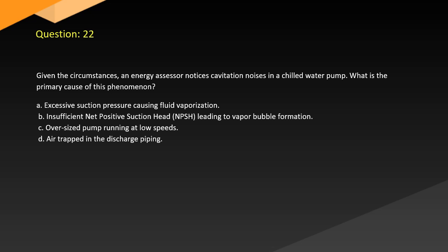Question 22. Given the circumstances, an energy assessor notices cavitation noises in a chilled water pump. What is the primary cause of this phenomenon? A. Excessive suction pressure causing fluid vaporization. B. Insufficient net positive suction head (NPSH) leading to vapor bubble formation. C. Oversized pump running at low speeds. D. Air trapped in the discharge piping.